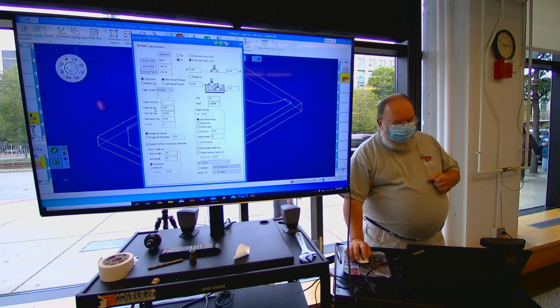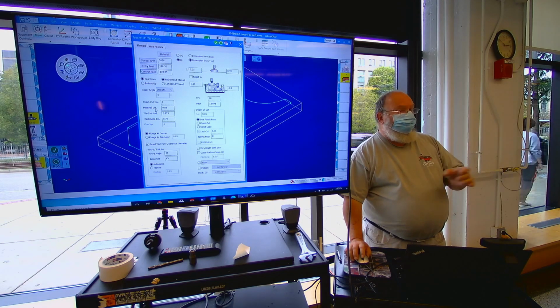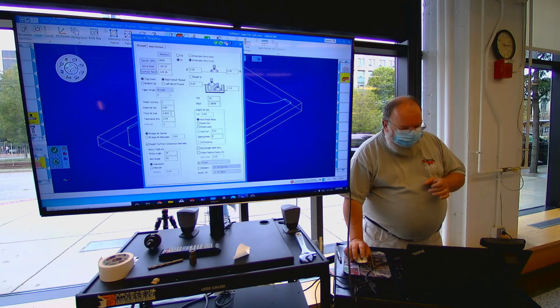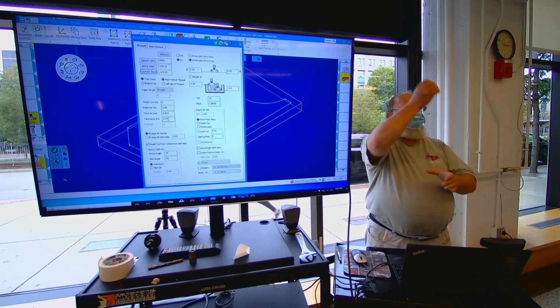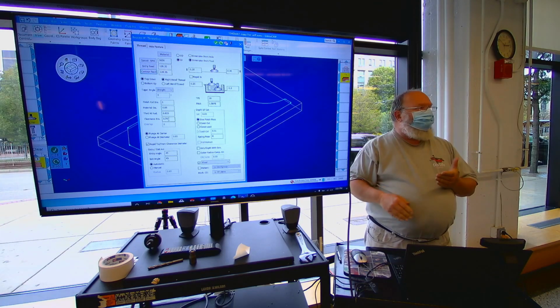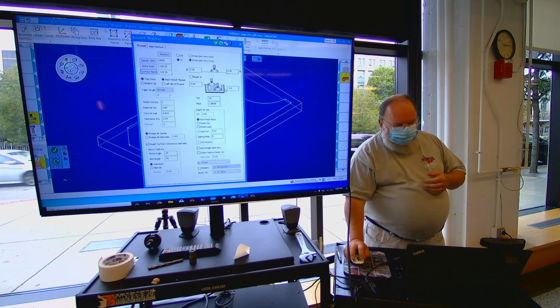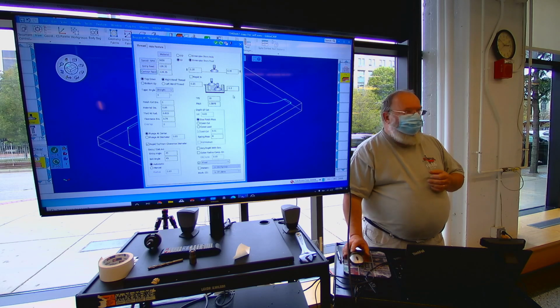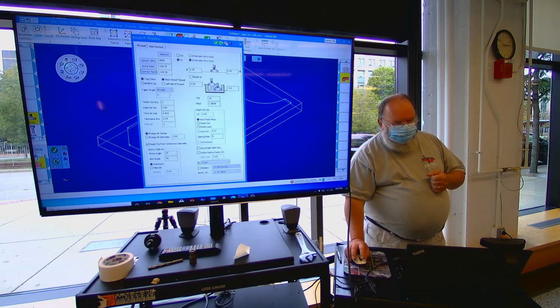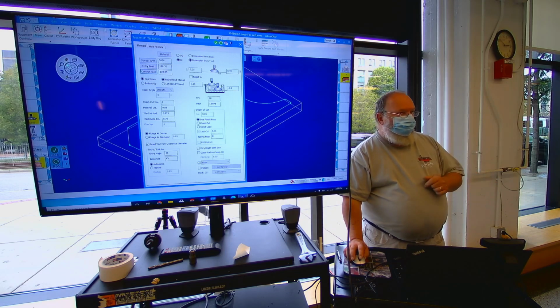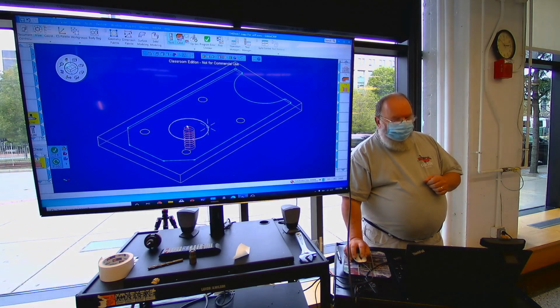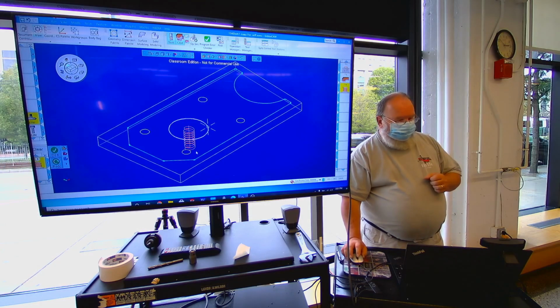Okay, the material diameter, or essentially the tap drill for this 1" 16 is .950. I'm going to tell it to go inside a 3/4 inch diameter circle when it retracts, so it doesn't mill the edge of my thread when it comes out. And over here, I see the depth is -0.3. Now the reason I do that, similar to the chamfer on this tap, is the tool is set to this surface. I don't get full thread until this surface is all the way through my workpiece. That's what the extra depth is all about. So I can say do that, and you see now I have that helical thread path that is generated by the machine itself.